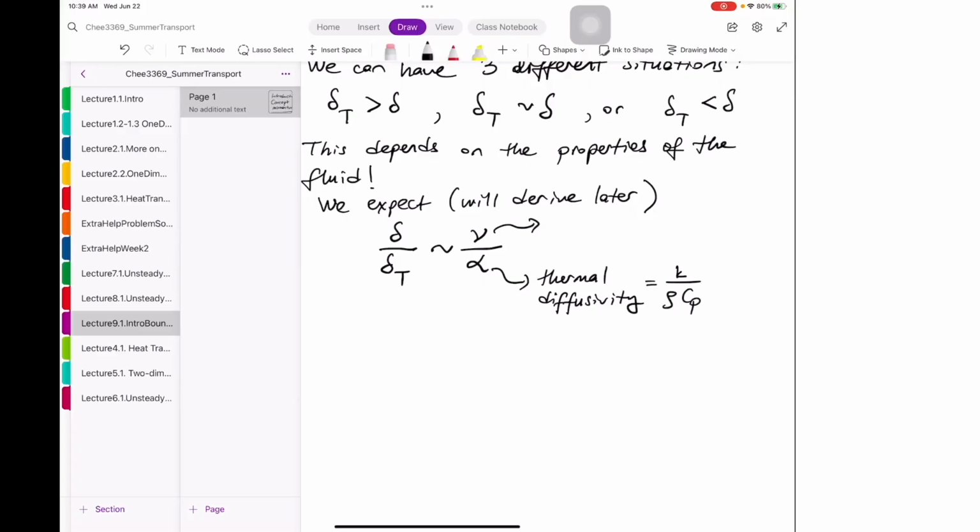We had an idea about the penetration with time, and at later times it penetrates more and more, and depending on the material property alpha, you can get a faster or slower penetration. That's why when we think about the thermal boundary layer thickness, alpha comes to mind, and you should compare it with the momentum diffusivity,